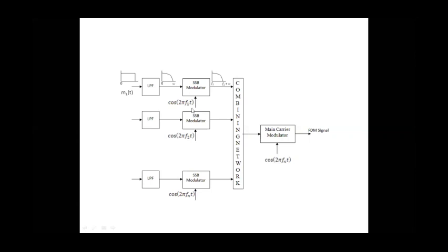In the same way, each and every message signal must be first band limited and then used to SSB modulate the respective corresponding subcarriers, to get the respective frequency translated signals. Okay. Second message signal, the corresponding band limited and then corresponding frequency translated version.